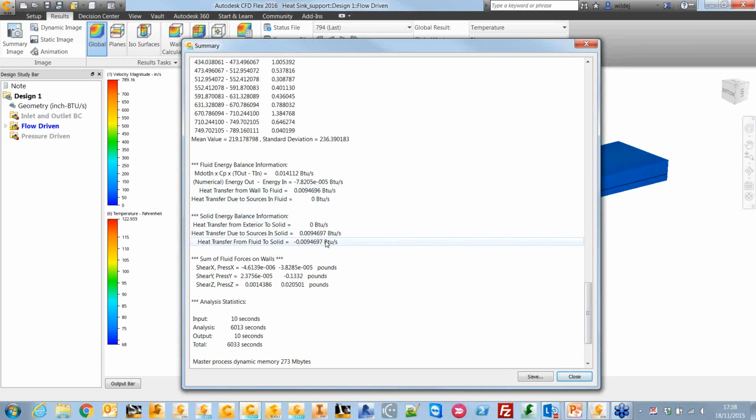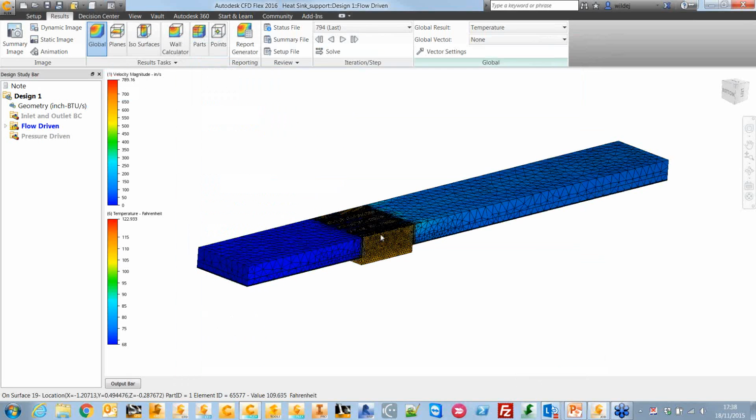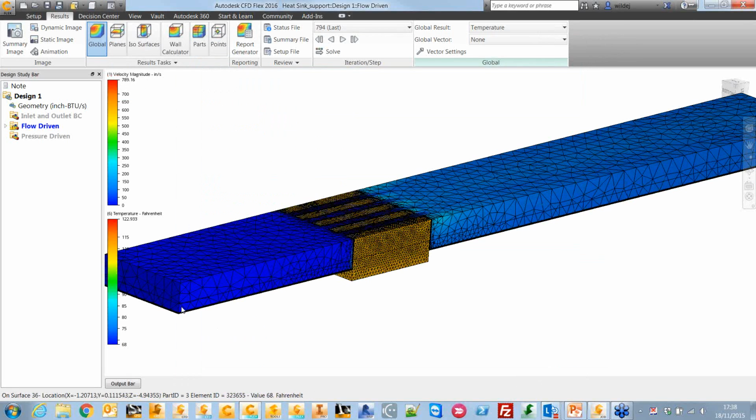Yeah, I was just looking at the m c sub p, and maybe we have something else goofy going on. This model wasn't run with the intent of being perfect. It's just kind of showing it off. But yeah, the reason for that is mesh. I'm pretty sure. It's pretty small, but it's going to be mesh. It's only 0.014 versus 0.009. Yeah, it's 10% error. That's not bad at all. Just for full disclosure, there's an inlets and an outlets section as well. Oh, yeah. So, yeah, it's pretty insufficient.